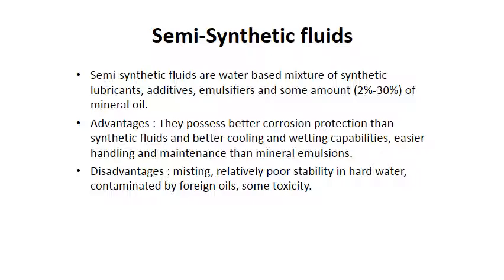Semi-synthetic fluids are water-based mixtures of synthetic lubricants, additives, emulsifiers, and some amount, 2 to 30%, of mineral oil. Advantages: they possess better corrosion protection than synthetic fluids, better cooling and wetting capabilities, and easier handling and maintenance than mineral emulsions. Drawbacks: relatively poor stability in hard water, contamination by tramp oils, and some toxicity.